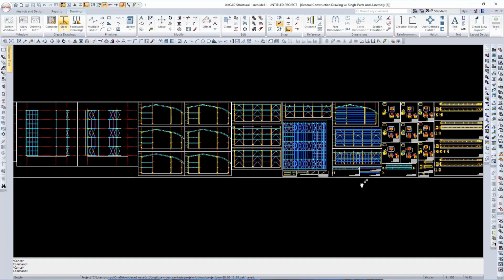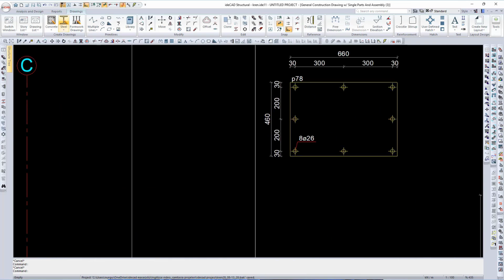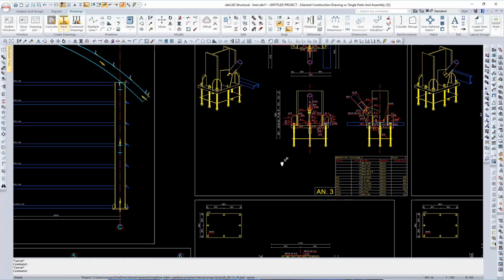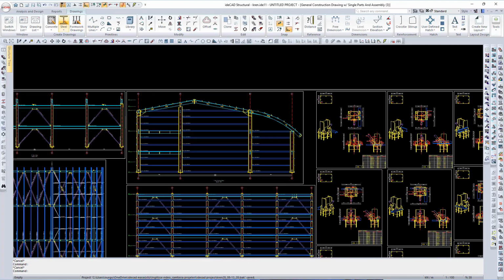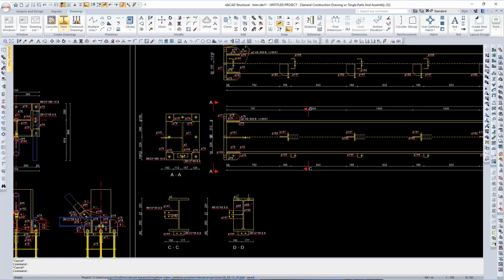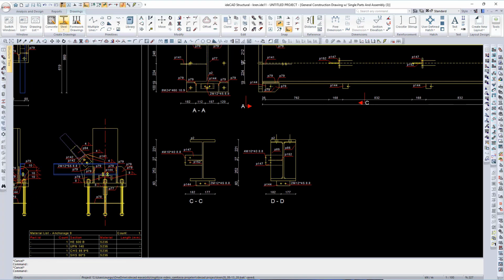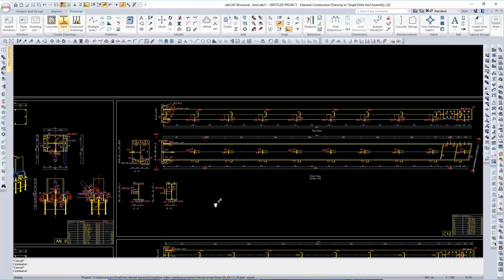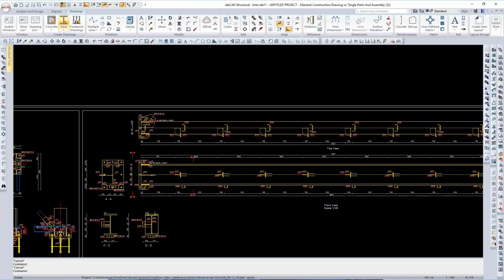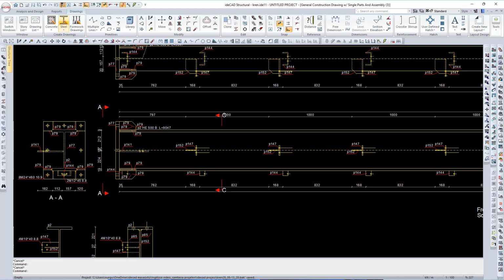Now let's move on to the point detail drawings. Here's the plate detail for one of the anchorage assemblies. We continue with assembly drawings and sheet generation. The software automatically generates sections and places dimensions on the drawings. Of course, you can manually edit these drawings as needed. Since it operates like a 2D CAD platform, you're free to make any modifications using standard drawing tools.